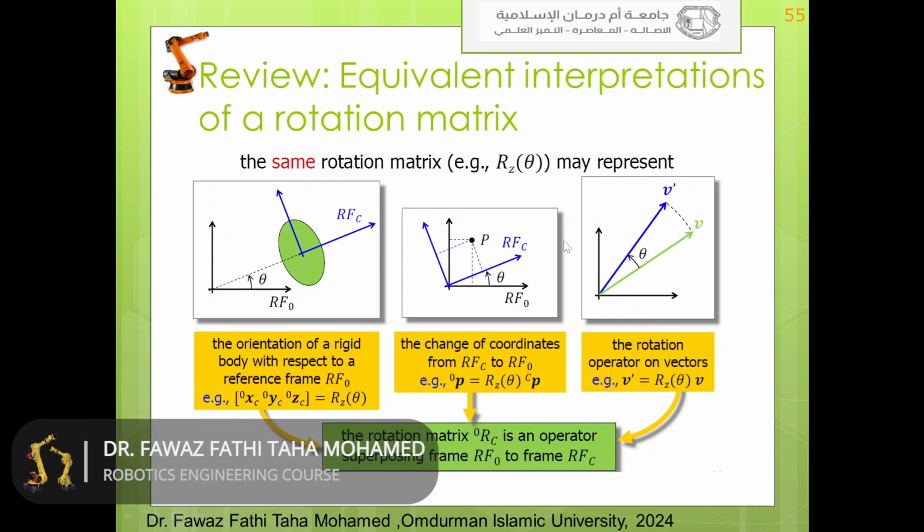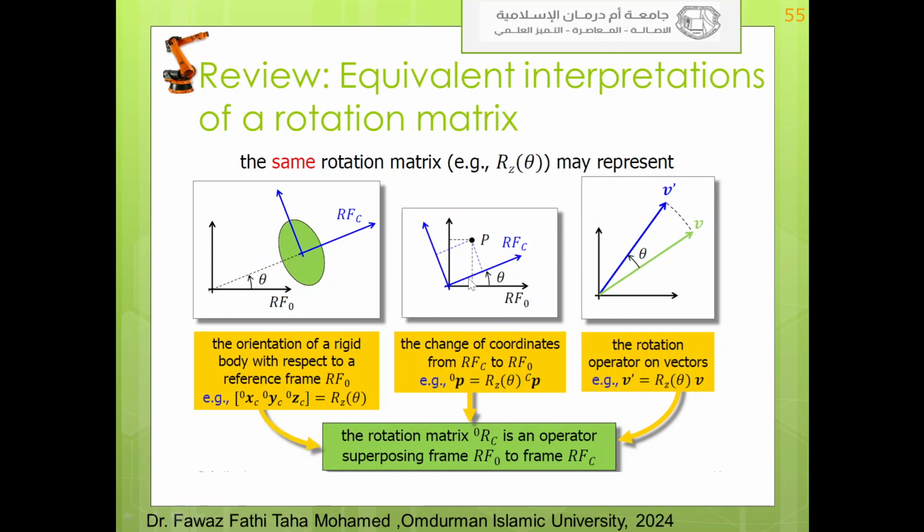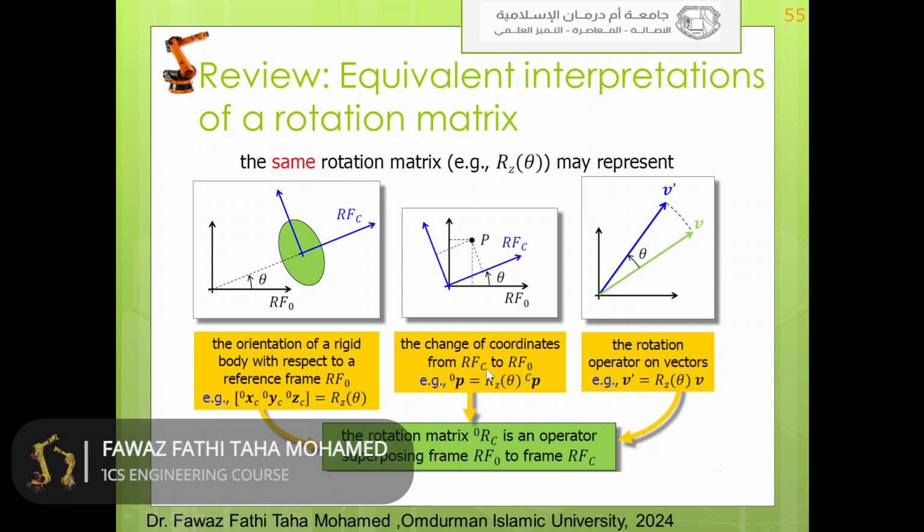As we can see here, because of the change of coordinates, the new coordinates are with respect to the previous or the current one. So R is rotated with respect to the previous or the current rotation matrix. So we can use this formula to prove the post multiplication case.